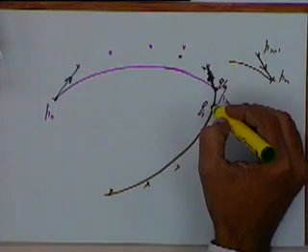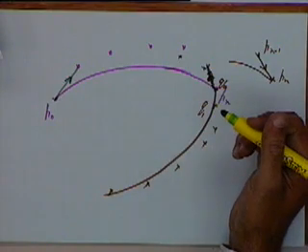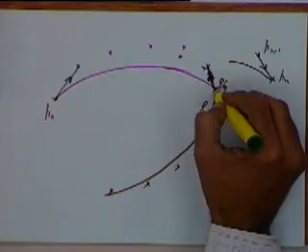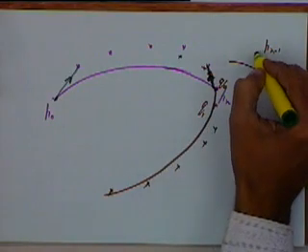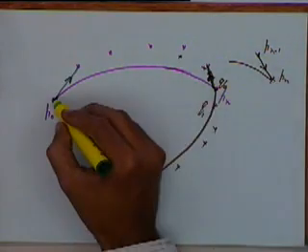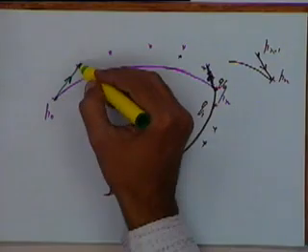We won't modify those points, or if we modify them, we will modify them such that they remain collinear. So in order to ensure C1 continuity easily, we give this constraint that at this point the tangent vector should be given by Pn minus 1 to Pn, and at this point by P0 to P1.